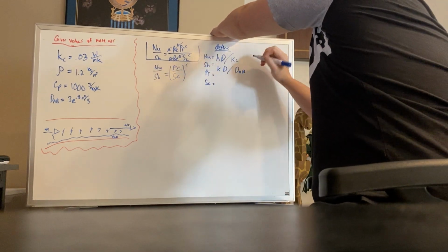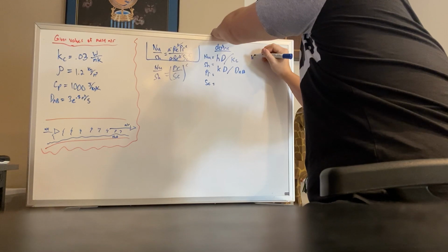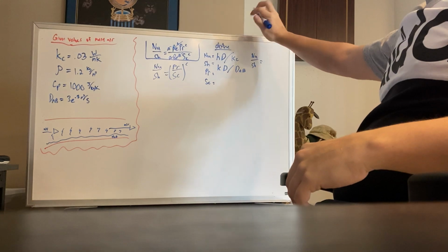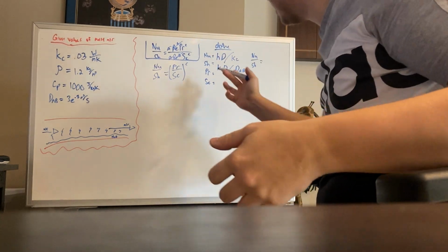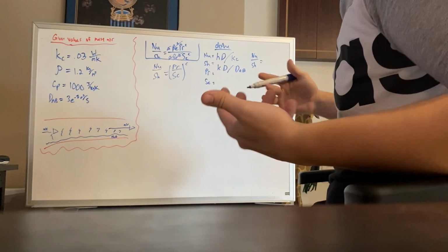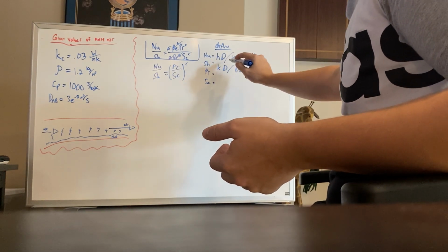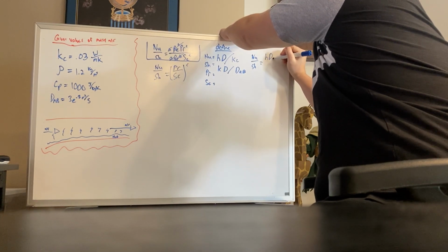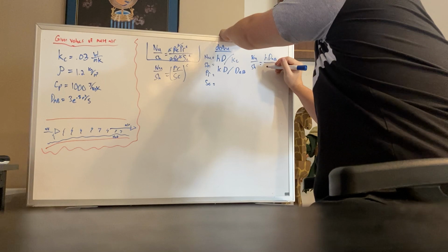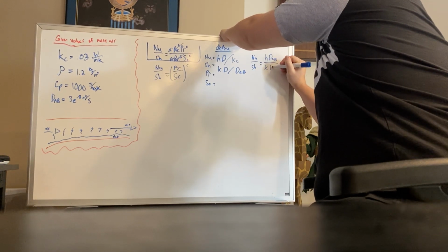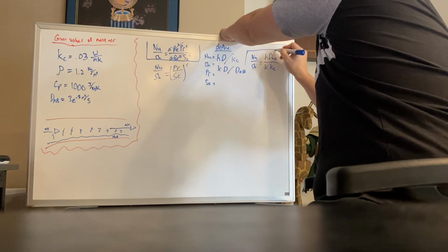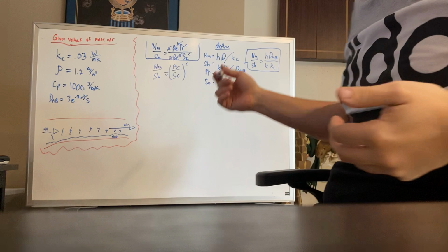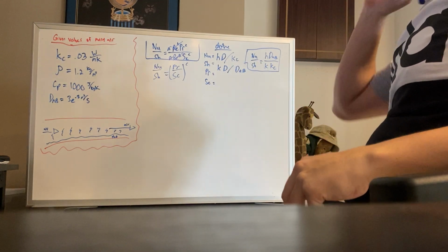So now that we have these, we can simplify them and pretty much combine them. So this Nusselt over Sherwood, I'll rewrite it here. We can do a keep-change-flip type of operation and get this to become more condensed. These diameters will cancel out and we will be left with the heat transfer coefficient multiplied by the diffusivity constant from A to B, all over the thermal conductivity multiplied by the mass transfer coefficient. So this is what we have currently for the Nusselt over Sherwood relationship if we rewrite it in different variables.